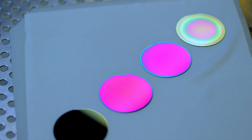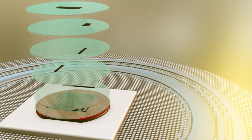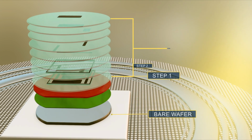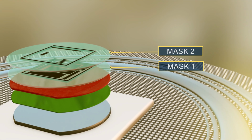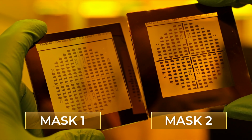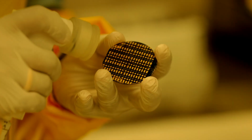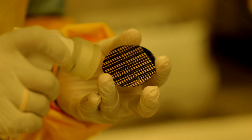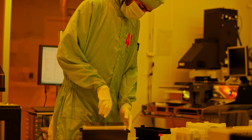It's now time to build our device on this wafer. It involves many steps with a mask defining every step. This is called a process flow. The entire mask set is designed and printed in advance. We will take you through the first two mask steps. The first step involves putting down metal pads at specific points on the wafer surface. A mask is first created on a chrome-plated glass plate.